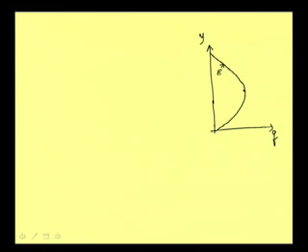Again, this point is critical depth. Once we know the critical depth, we know one more point: depth above critical depth is subcritical, and below it is supercritical. With the change of unit discharge, depth is changing, that is obvious.